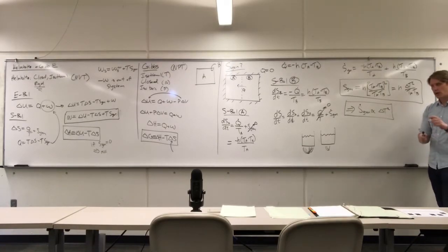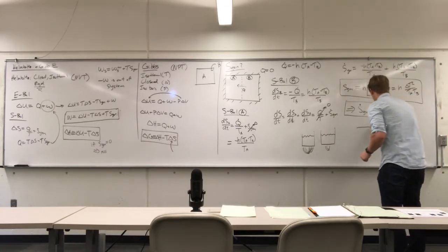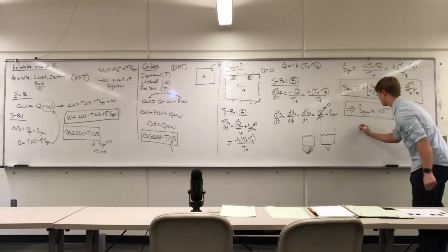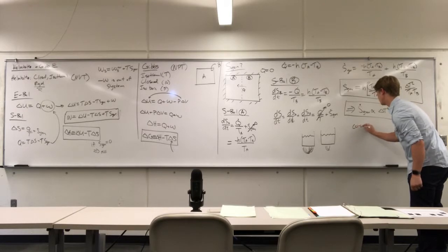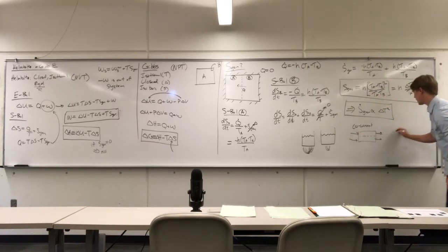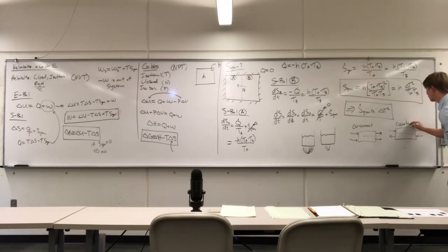So that's also why, when you have a heat exchanger, which of these two designs is better? Co-current or counter-current flow? So if I have co-current, I have two streams flowing in the same direction, versus countercurrent, where I have one stream flowing one direction and the other flowing the opposite. Why is countercurrent the more energy efficient way to do it? So at every point, the gradient will be smaller than in the co-current. Exactly. So from a thermodynamic perspective, countercurrent is the way to go, always.